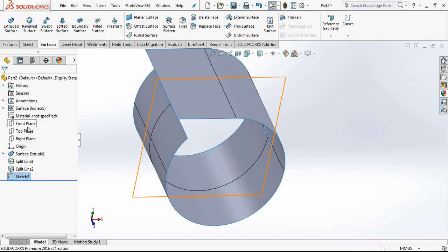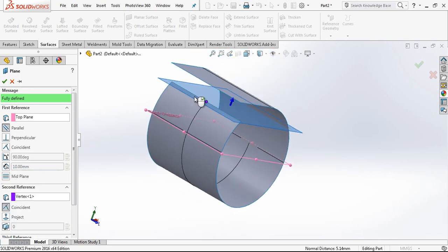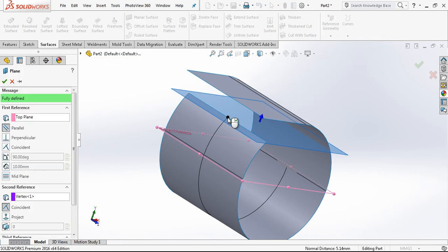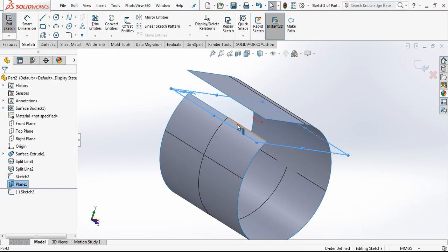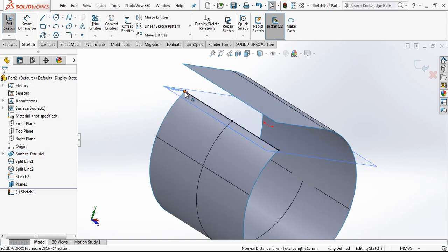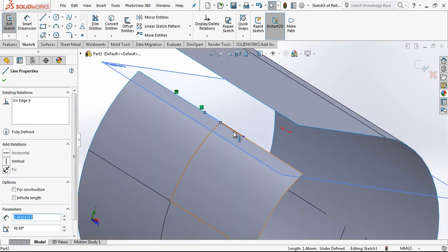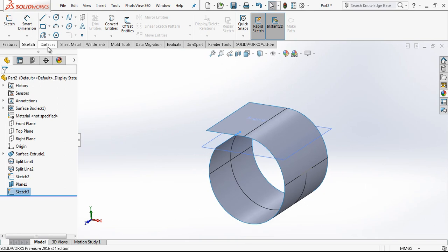and in top plane we are opening a plane with the help of our top plane on this point, and again top plane reference geometry plane, and we are opening here again a sketch, the same method that I'm using, just touching the points and moving lines, later making them equal, and the width here between 2 points will be 1.5. Basically our sketch is ready.